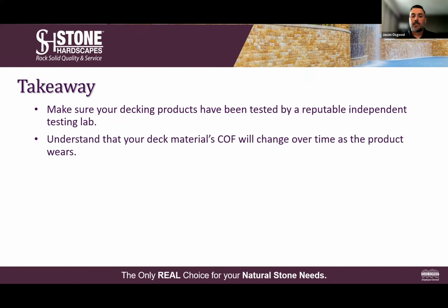Understand that your deck's coefficient of friction will change over time as the product wears. Again, we talked about it a few minutes ago. If you get a product like an Ice Extreme, which is a sandblasted material, which gives you an extra level of assurance of a grip, over time, that sandblast, that texture will wear.